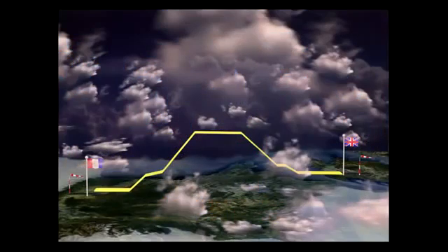Normal law is modified depending on the phase of flight. It operates in three modes. Ground mode operates on the ground when the aircraft is electrically and hydraulically powered. Controls are conventional. Flight mode operates in the air after a gradual transition from ground mode, just after liftoff. Flare mode modifies flight mode to introduce a conventional feel to the landing phase. Will be discussed later in this module.